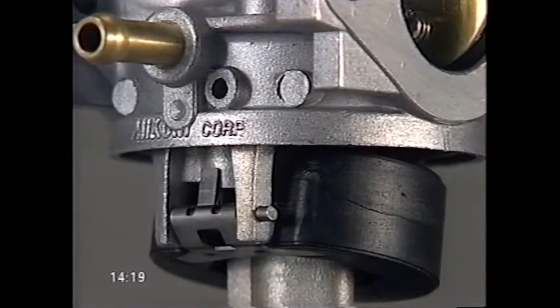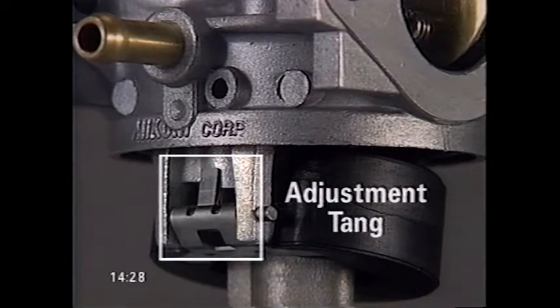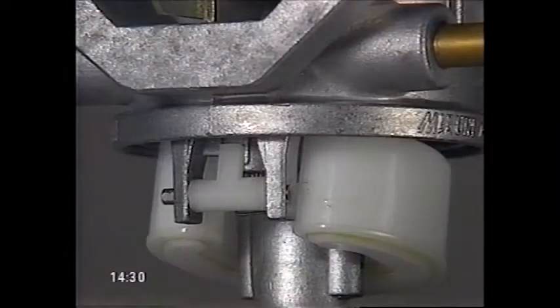On some Kawasaki carburetors, usually those with a black-colored float, the float level may be adjusted by bending this metal clip that attaches to the needle valve. Some carburetors have white floats, which cannot be adjusted because the tang that positions the needle valve is made of plastic.